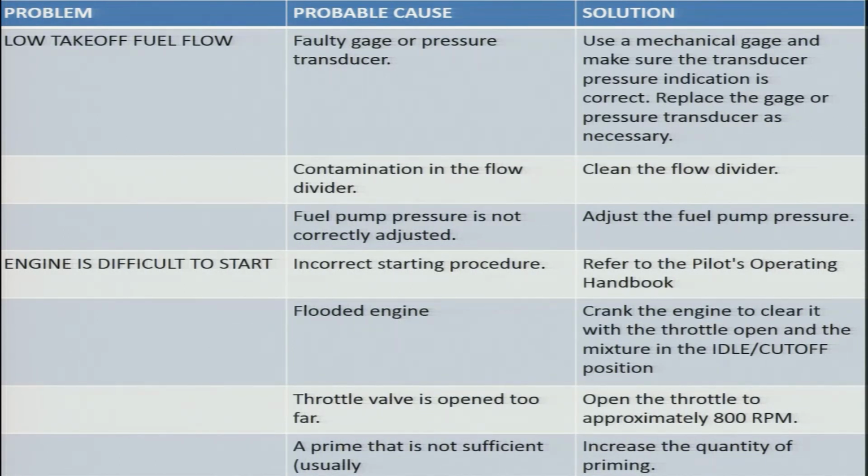A very common problem is that we are attempting to start and the engine is not starting, or the engine is difficult to start. Then what may be the reasons? There may be several reasons. Incorrect starting procedure. The procedure through which we are starting might be incorrect. Flooded engine. The engine is flooded. That means more than the required fuel has come to the engine.